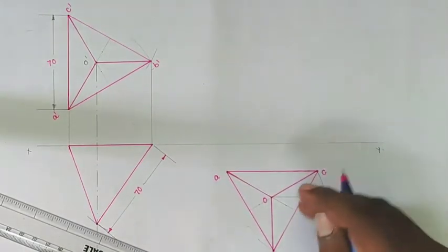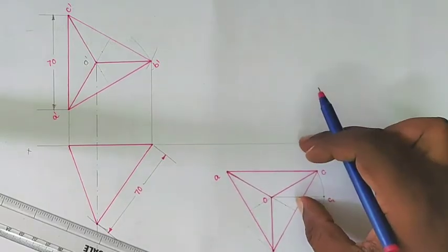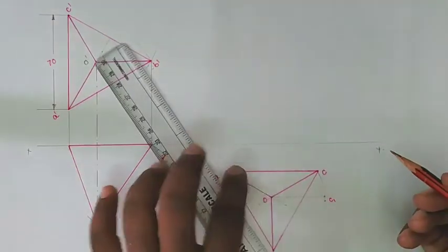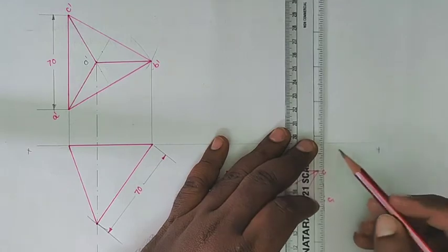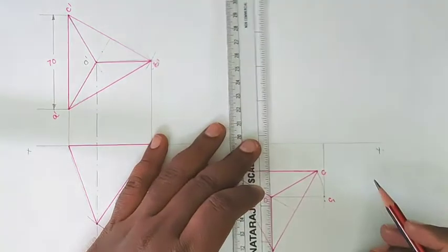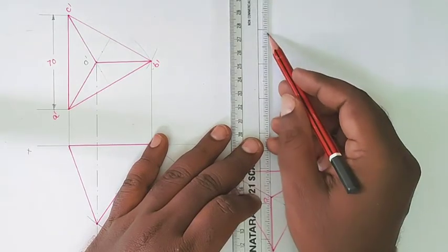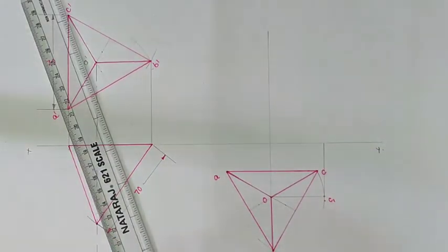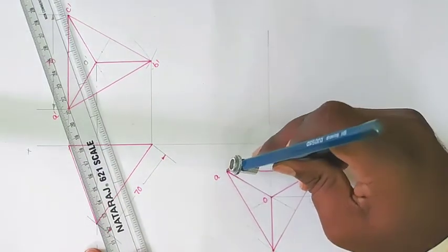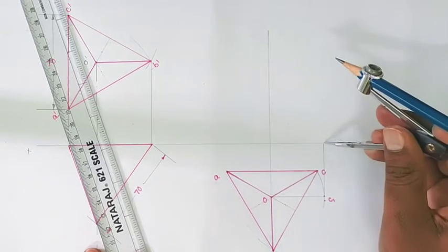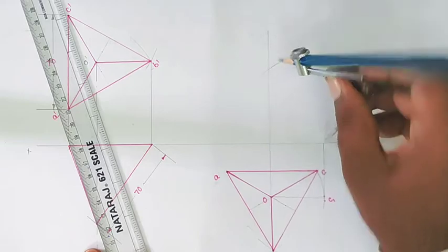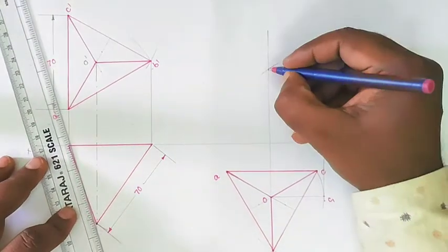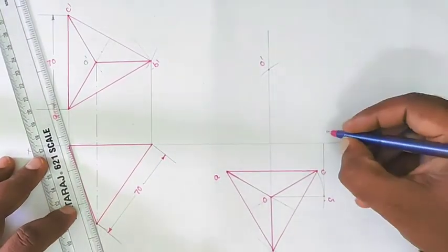How will it look with respect to the reference line? So OC1 will be parallel to the reference line. From point C1 we will draw the vertical projection line up to the reference line, and we will draw the axis line with the length of the edge. So here, through the center, I am drawing the axis line like that. From the reference line, with the edge length 65 mm, from this point we will draw the arc. So locate the center O dash. So this is C1 dash.